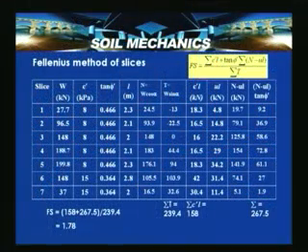Now, having looked into it, this is how the Fellenius method of slices can be adopted. In case the soil has more than 3 or 4 layers, and it is required to be analyzed using Bishop's method, then computer programming is required, for which standard codes are available, and based on that the analysis can be performed.